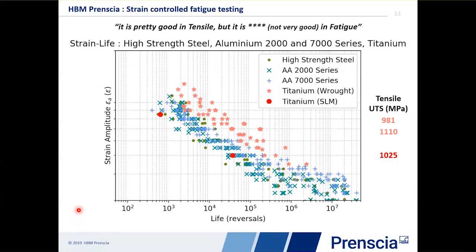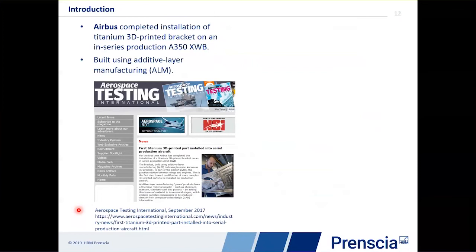And that was pretty much what we were hearing from all around. You produce additive manufactured materials, they were good, they obtained the tensile stresses that you want, tensile strength, but when you subject them to fatigue, then the lives were orders of magnitude lower than the equivalent wroughts. However, there are many advantages of additive manufacturing, and the industry hasn't stood still.